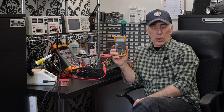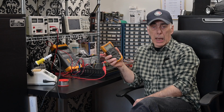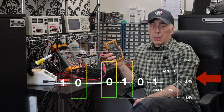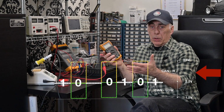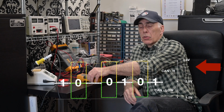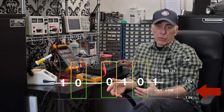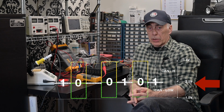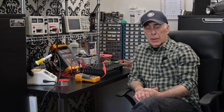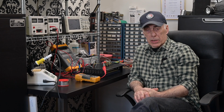If you measure CAN low towards ground and you measure CAN high towards ground, you should always have something around 2.5 volts and a bit more for CAN high, and you should have most likely something between 1 volt and 2.5 volts for the CAN low, and I'll show you that in a minute. Of course, that is not the best solution. The better solution is to use an oscilloscope, and it doesn't have to be an expensive oscilloscope.